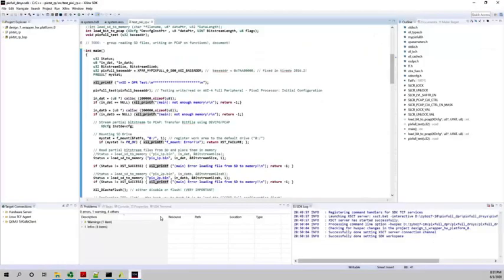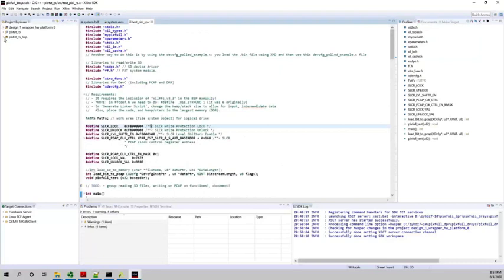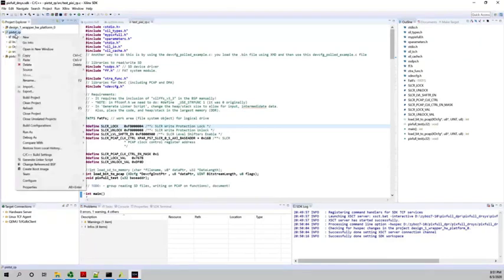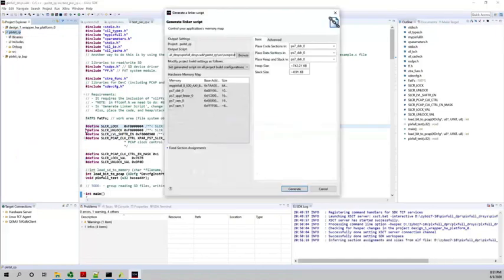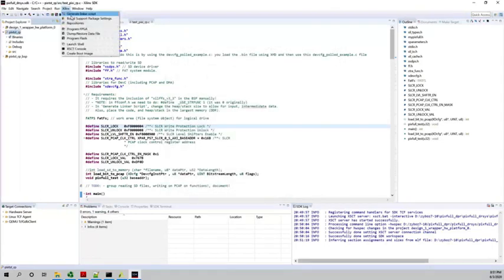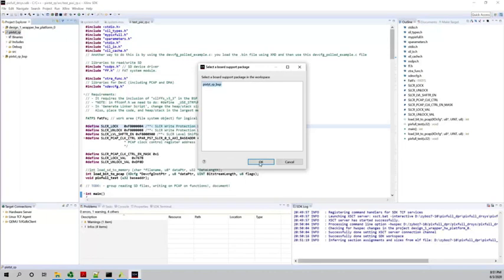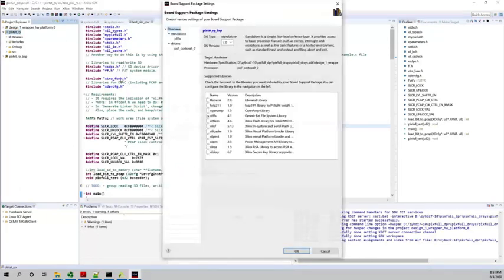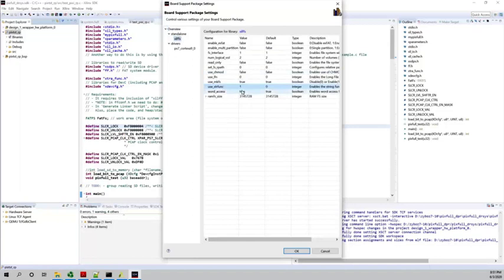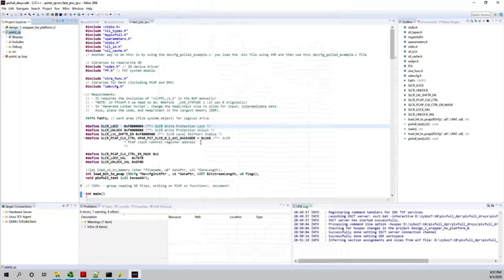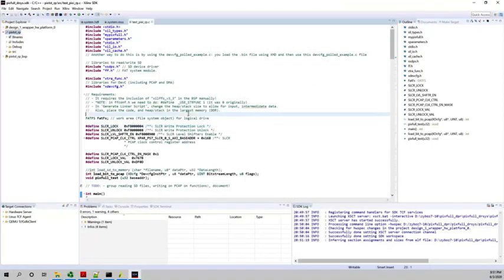And here is the software application. So I already created that, by the way. I think the only thing you need to be careful about is generating the linker script, of course. Everything should be in the DDR, and you should have at least 700 kilobytes for your heap and 4 kilobytes for your stack. Also, because we are using the SD card, make sure that in your BSP you are using the xilffs library with the use string function enabled. You have to replace a 0 here by 1 that is here. By the way, those steps are already specified in tutorial number 5, I think. I already explained that, okay?